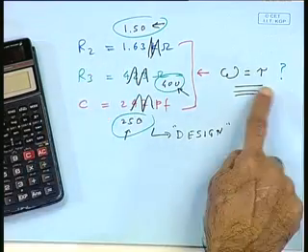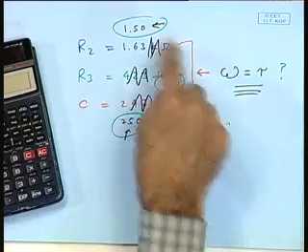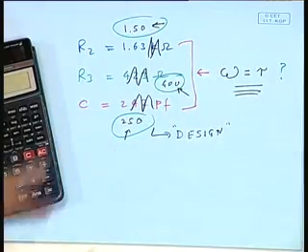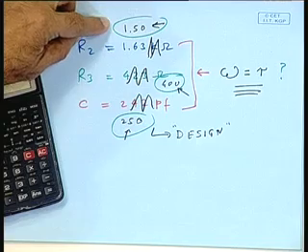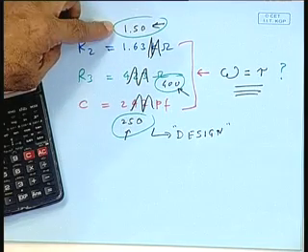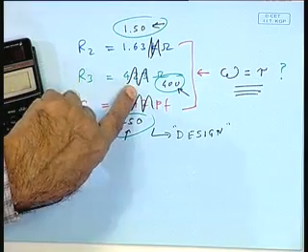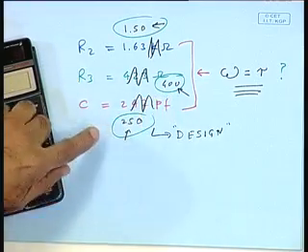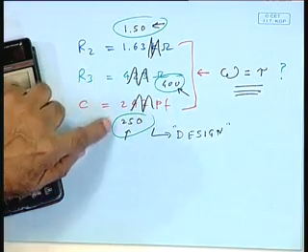Well, luckily, Taguchi's robust design says yes, you can. You've got to be slightly lucky, but generally speaking, engineers can start with a design that is like this, the exact design that will give you the exact performance, and make the design robust. For that, you will probably have to manipulate certain things. And you can then allow this value to be slightly different from 1.63, like 1.50 here. Instead of 423, it will be 400 there. Instead of 242, it will be 250 here.